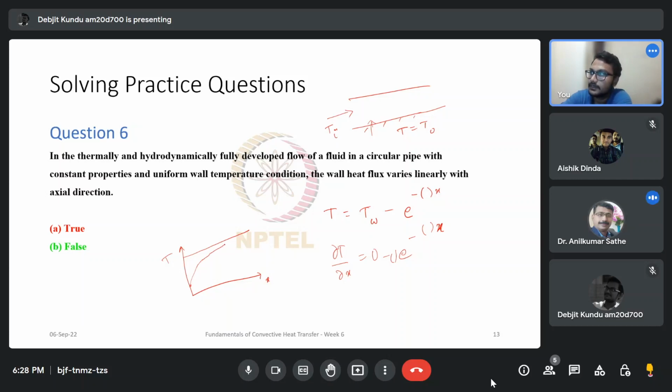So the difference would gradually decay, and the rate of that decay would decrease with the difference itself. At x equal to infinity, we can hope that this would actually become equal to T naught, which is the temperature of the pipe itself. So before that, it would approach that temperature. This is purely from a physical argument, not a mathematical one. Yes, sir.